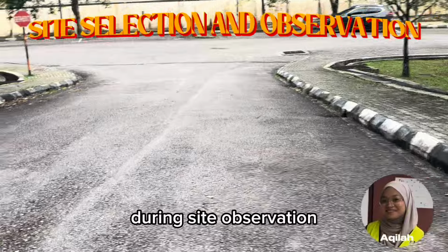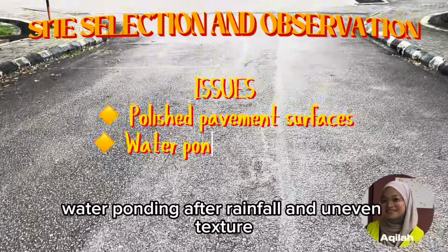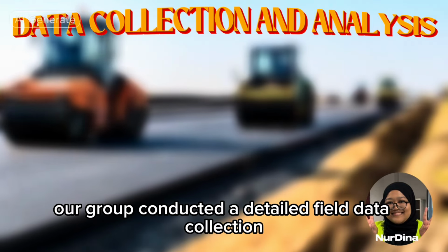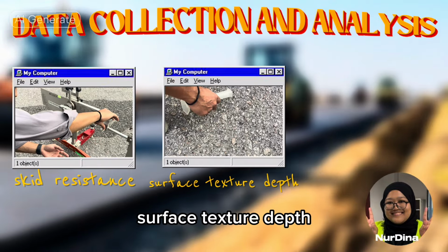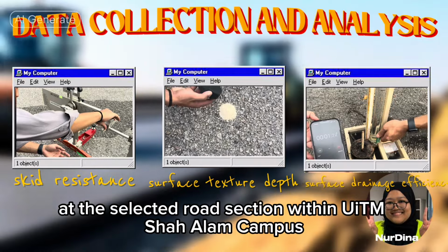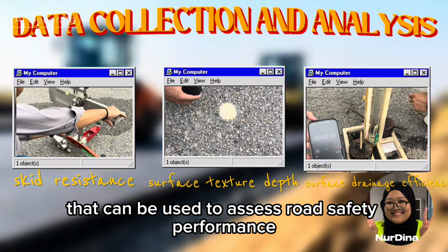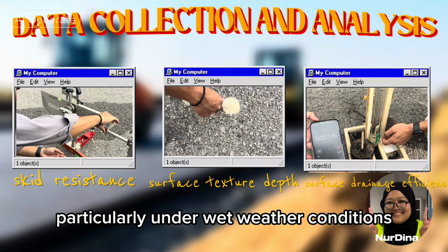During site observation, we identified issues such as polished pavement surface, water ponding after rainfall, and uneven texture, which could potentially compromise road safety. Our group conducted a detailed field data collection to evaluate skid resistance, surface texture depth, and surface drainage efficiency at the selected road sections within UiTM Shah Alam campus. The purpose of this data collection is to obtain actual pavement condition data that can be used to assess road safety performance, particularly under wet weather conditions.